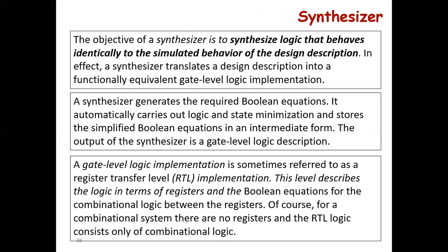So the main objective of the synthesizer is to synthesize the logic that behaves identically to the simulated behavior of the design description. In effect, a synthesizer translates a design description into a functionally equivalent gate level logic implementation. A synthesizer generates the required Boolean equations. It automatically carries out logic and state minimization and stores the simplified Boolean equations in an intermediate form.